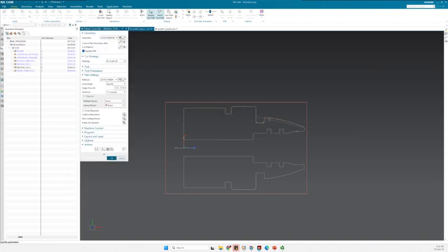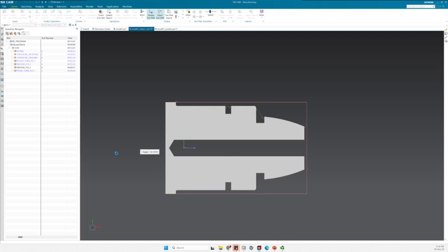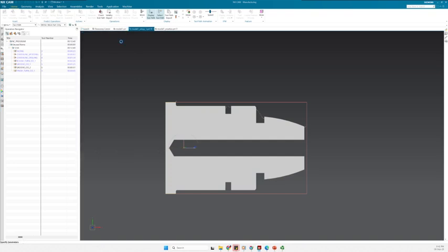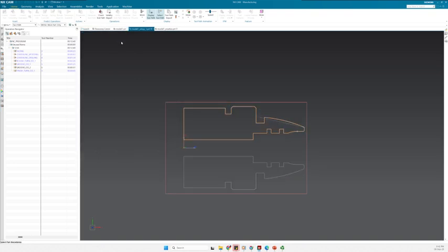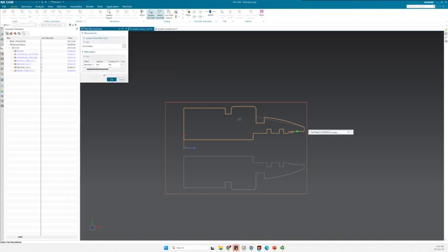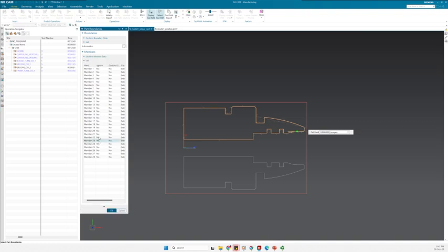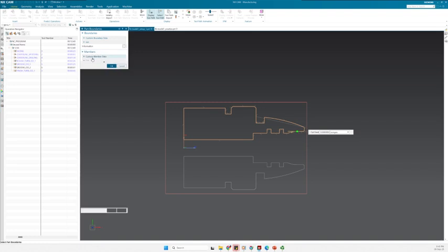And now I can see that there is a problem here. So it somehow jumps to this one. So this is not what I'm looking for. Yes, so definitely this is an error. So I don't want that. Let's go back and cancel this member 23. I guess it was the bottom one. Even though the bottom one should be ignored, I think when I define these 3 different regions, that is how it somehow wants to jump to the next region. So this is the one, so do not ignore this one.